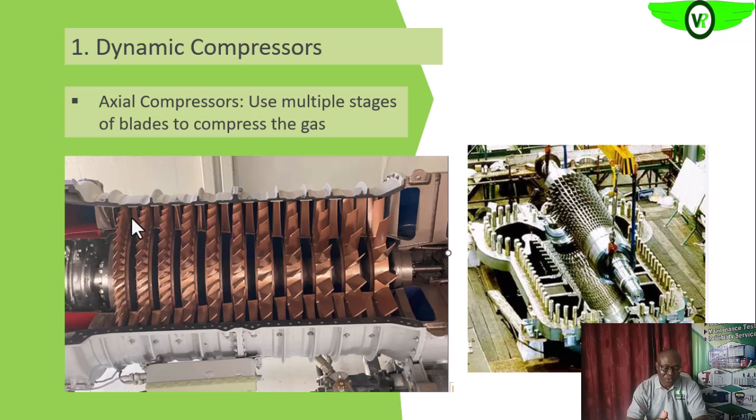Okay, so that temporary stoppage, like we said, with the application of Bernoulli's principle again, will result in an increase in pressure. So this diffuser, which is the stationary blade now, okay, as it is leaving this stage, the gas pressure will be increased to a level.